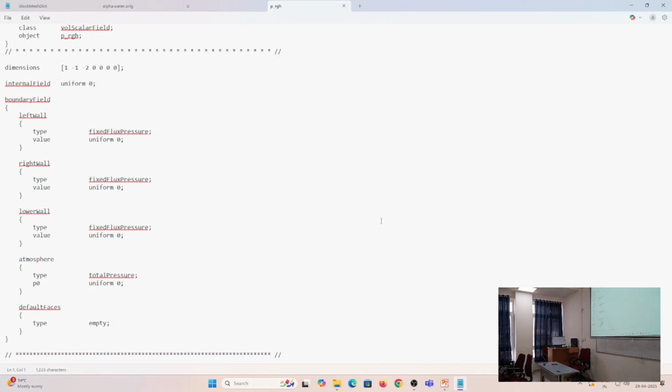So, once we specified the no slip condition, we have defined the value of velocity at that point. So, that is why pressure will now be computed based on the discretized set of equations. So, what we are simply telling is that at the boundary node and just in the internal node, pressure will be coming from the computations within the domain.